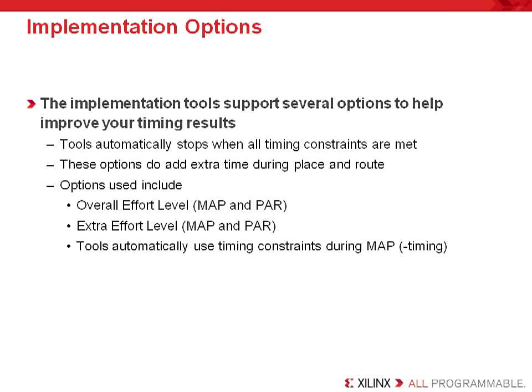So again, the intention here is to work harder during the map phase and the placement phase, rather than the route phase, because in the end it's much more powerful to use timing constraints and use these options during map and placement to get better timing results than to just reroute the design.